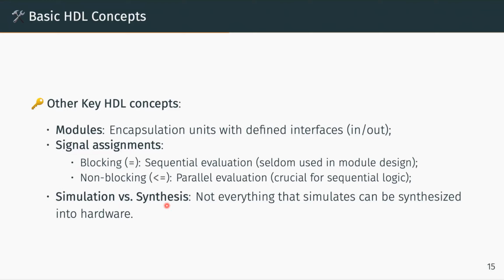Another thing is that simulation is different from synthesis. Not everything that simulates can be synthesized into hardware. For example, if we write code saying that at a certain clock time the signal needs to be high, this can't be synthesized into hardware because the hardware does not know what time it is. So simulation and synthesis are different, and we need to write synthesizable code in module designs.